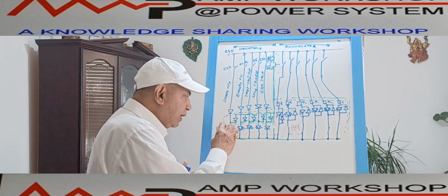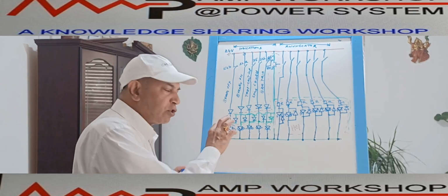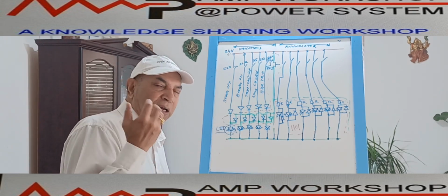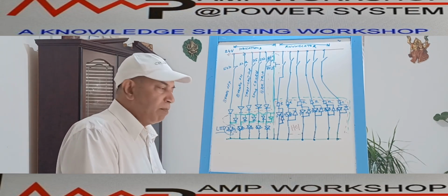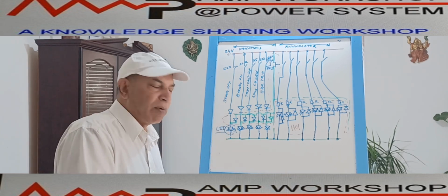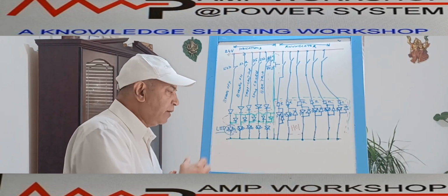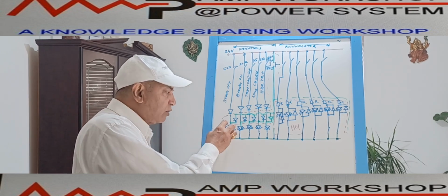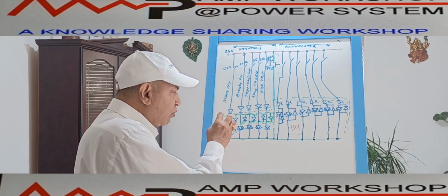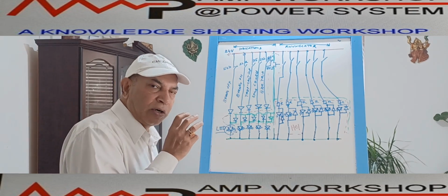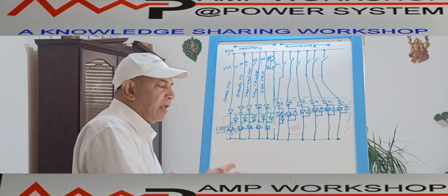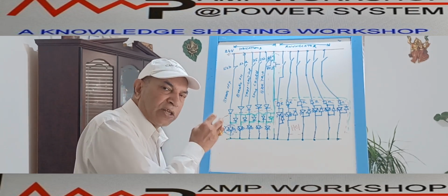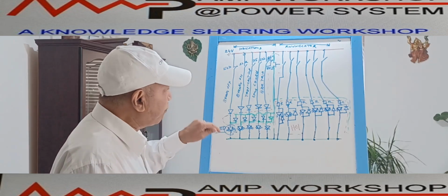So the withstand voltage is normally a maximum of 3 volt, and the current flowing through the LED will decide the intensity of the lamp. But if you pass a high current through the LED beyond its capacity, then the LED will burn itself on its own. So this is a self danger. That's why when we connect the LED, we have to consider these two parameters: reduce the voltage to the required voltage of the LED, and keep the current flowing through the LED within its withstand capability. I am coming to how we do that.